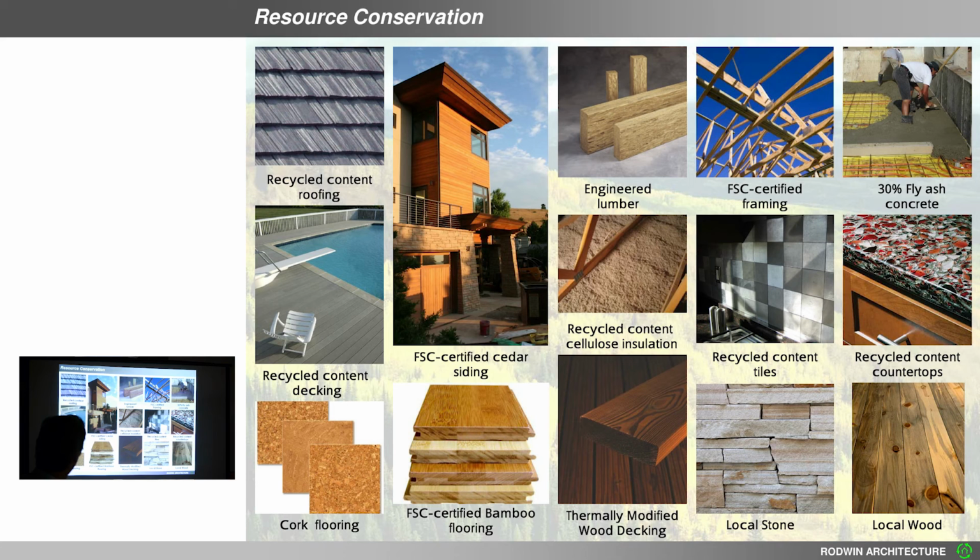Bamboo flooring. Do you have success with bamboo? Yeah, we do. I've got it in my house. Yeah. All hardwood flooring in Colorado has a hard time. Bamboo is a little bit of a newer product, so it tends to be a little less dimensionally stable than, say, older growth products or more conventional wood flooring. But really no worse than conventional hardwood flooring. Wood flooring in Colorado it's hard to get it to not gap in general.